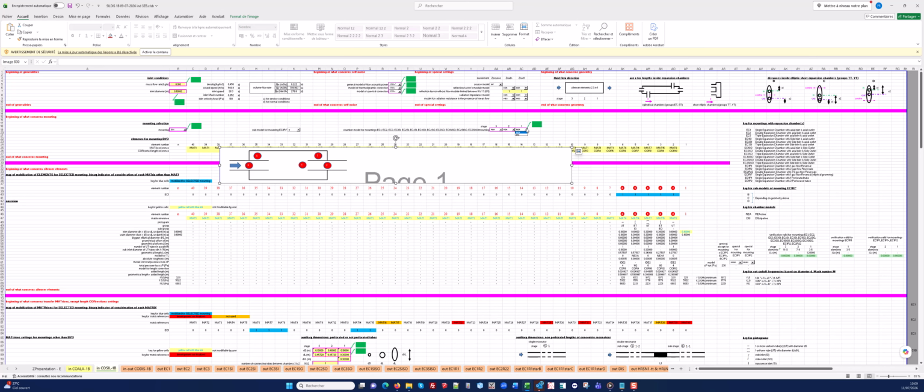Here we can select a reactive chamber, which could also be dissipative. In this case, the output results of module 1 should be used as input data for the present module. As soon as we have selected the mounting EC1, the appropriate elements arrangements are shown here, with the element numbers highlighted in red and with the corresponding matrices and parameters.